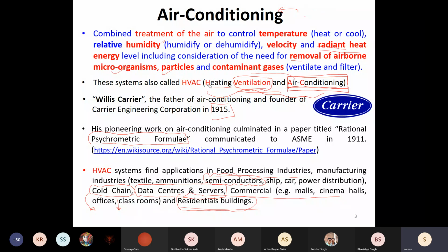Okay, imagine that you have to cool the air where you have steel making going on. You are standing next to a blast furnace, or you are standing under a tinned roof. Then it is not just cooling the air, sensible cooling of the air, you also have to block the radiations.